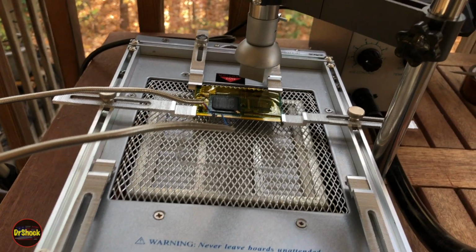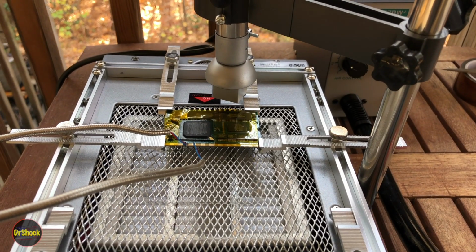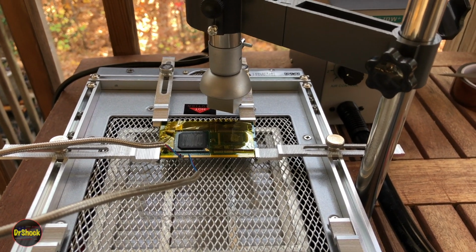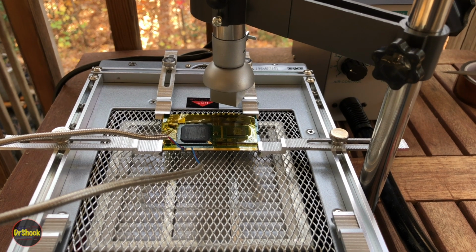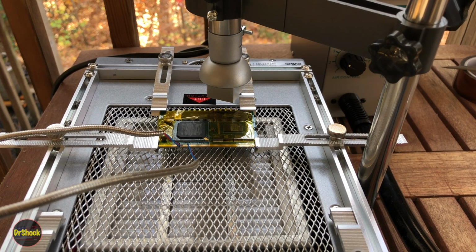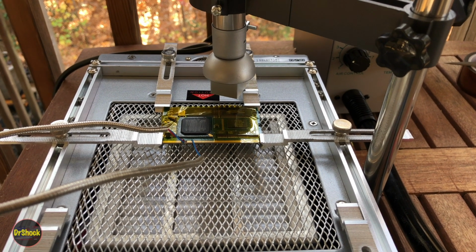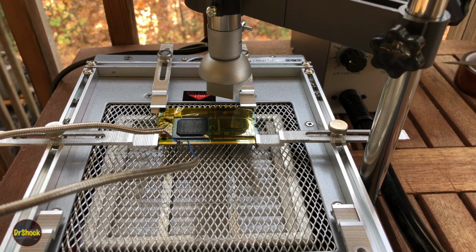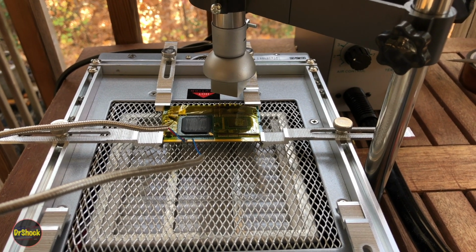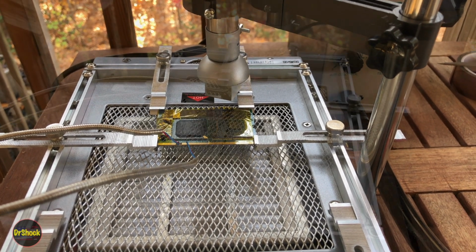We're basically going to take this guy up to 183 degrees or so preheat. Then we're going to bring the hot air over the top to take it up to the 220. That'll liquefy the solder, and that should get us at the point where we've done the secondary reflow. I'll put you guys up on the stand, and you can see that secondary part when we get to it.